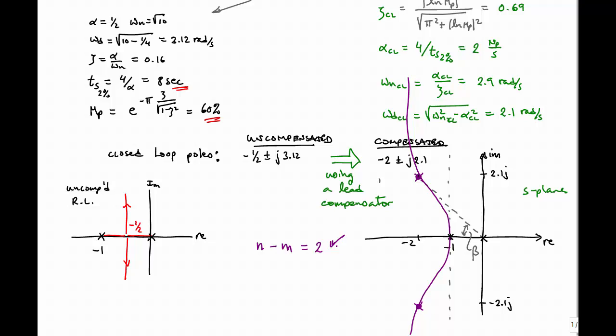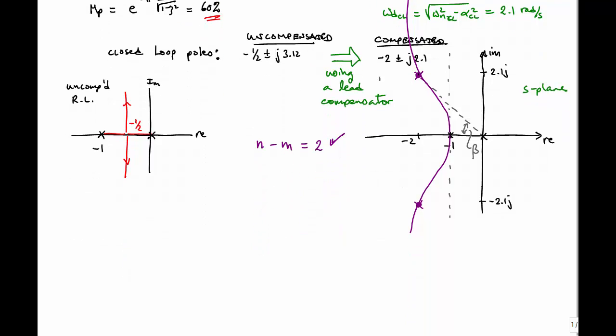And if I added just a 0, which is actually what I need to do to bring this root locus toward the left, then now I would only have one root locus path to infinity. Let me show you that, because some of you may be wondering, why wouldn't we just do that? It seems like a more simple system.